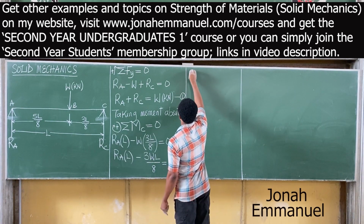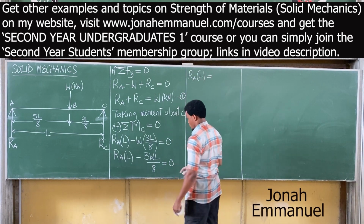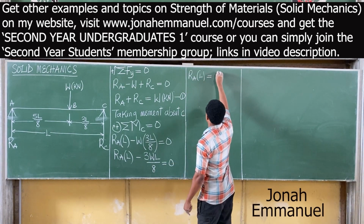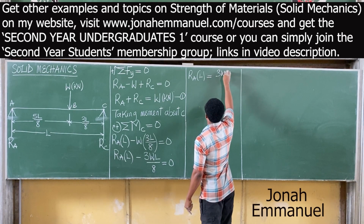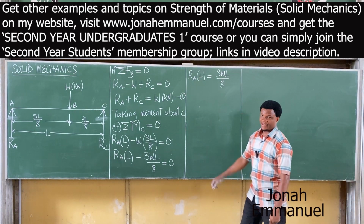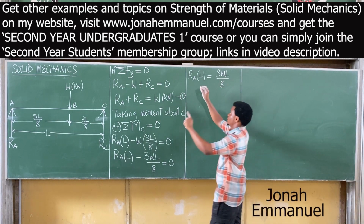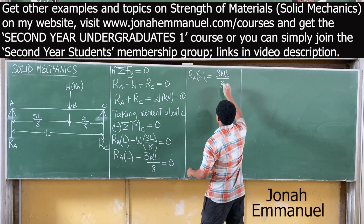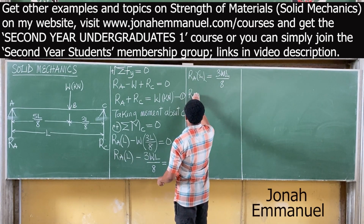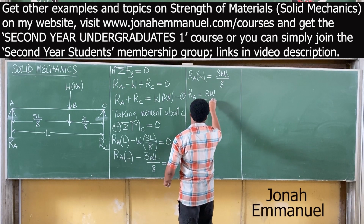We have that RA times L is equal to 3WL all over 8. If you look at this, I have L at this point and this point, they can cancel out. So they are gone. I'll have that RA is equal to 3W over 8.